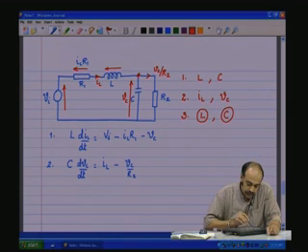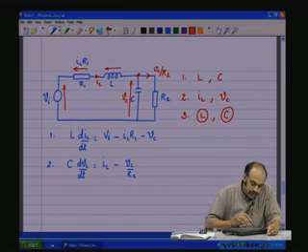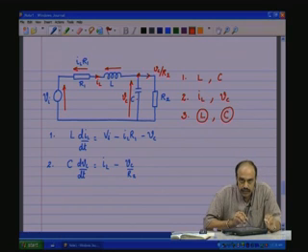So, therefore, try to identify that state variable which will decide the voltage and so on. And as R is in series with L, the state variable IL is used for finding the voltage across R. So, IL R1 is the voltage across that one. So, all the elements, the voltages across them have been identified.